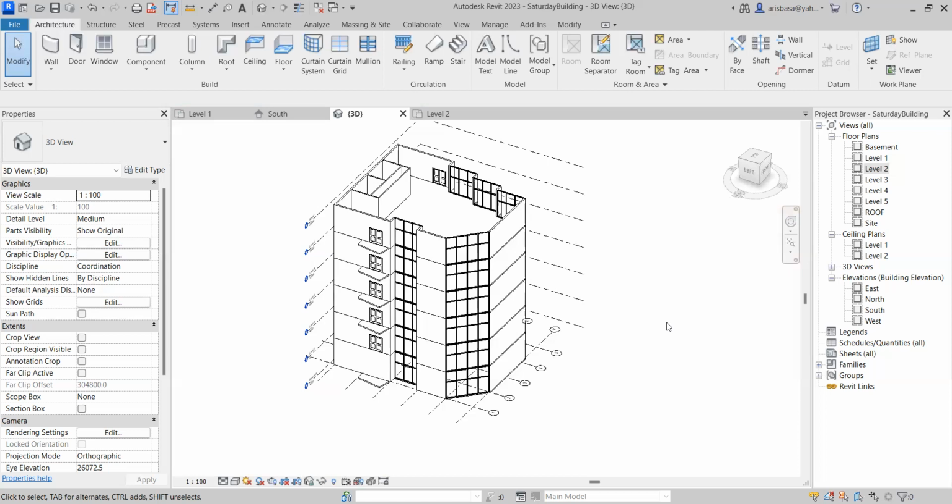But this software only supports Revit models, right? You told me Navisworks can support all of them, so you can bring them together to compare the quality, right? But Revit can only support other Revit. So if we want the simple clash detection, we can convert here. But for advanced, we can only use Navisworks.